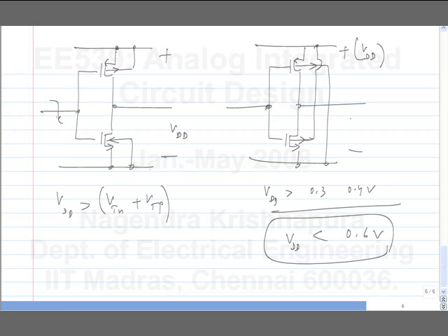Another way of getting circuits to operate at low voltage is to make low threshold voltage transistors. But one of the problems is always that if you make a very low threshold voltage, you can turn it on, but you can't turn it off easily. So I think only after all that is worked out will it be used. But it's probably used to some limited extent somewhere. So that's actually good for analog circuits. In analog, you don't care about turning off things, right? So there should be fewer restrictions on doing this type of thing for analog.